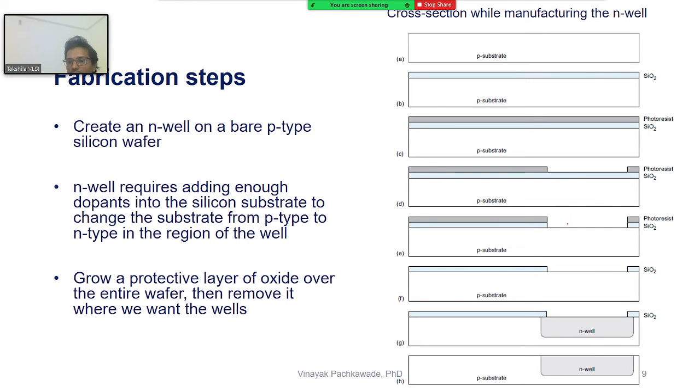As we go to the next step, I put this wafer in hydrofluoric acid. This is HF acid, and this is the wafer. In this portion, the SiO2 is etched, because hydrofluoric acid is known to etch SiO2. This is the chemical process step that you are doing. So SiO2 will be etched away. Once that step is done, you just remove the photoresist. You just rip it off, take it off. So this is the final figure that you have.